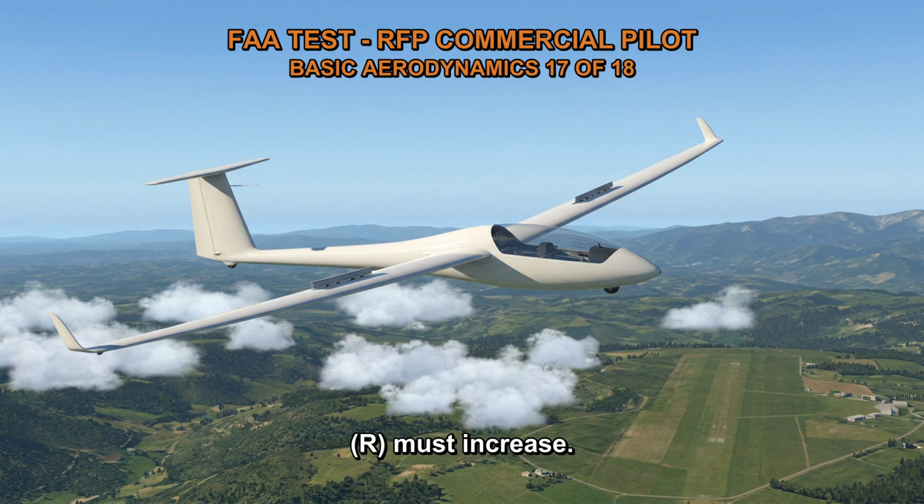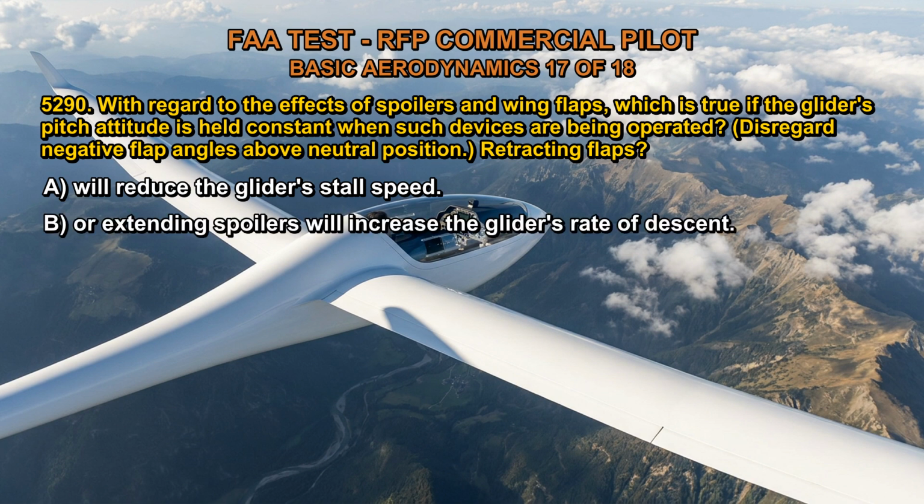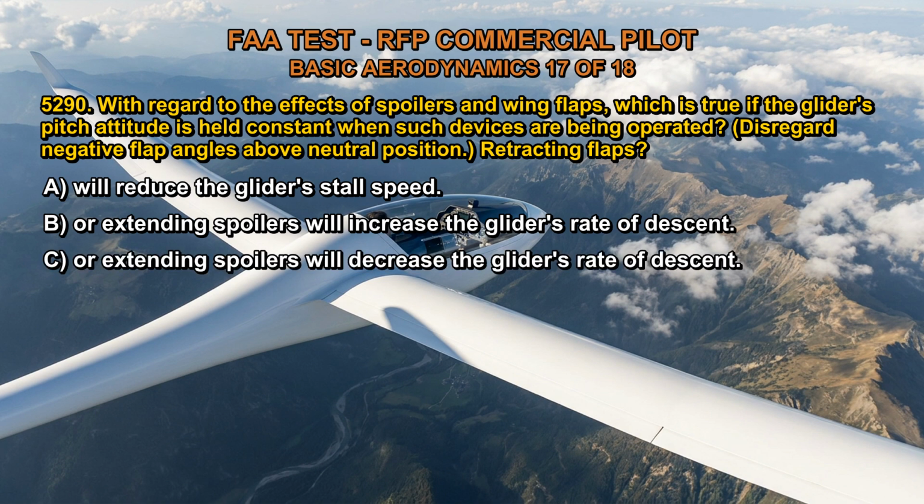5290. With regard to the effects of spoilers and wing flaps, which is true if the glider's pitch attitude is held constant when such devices are being operated? Disregard negative flap angles above neutral position. Retracting flaps? A. Will reduce the glider's stall speed. B. Extending spoilers will increase the glider's rate of descent. C. Extending spoilers will decrease the glider's rate of descent.